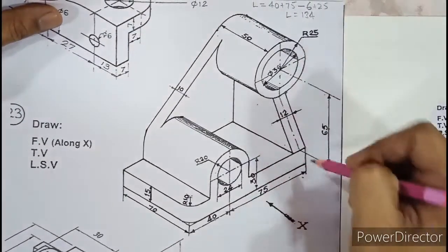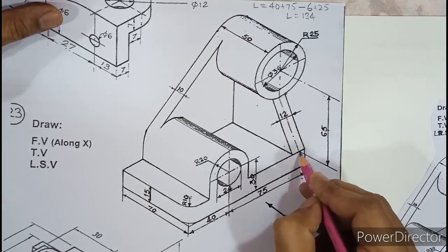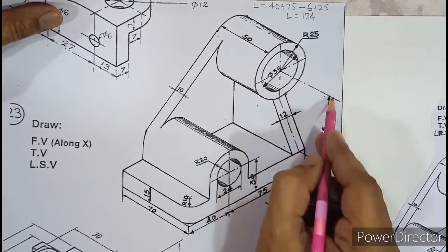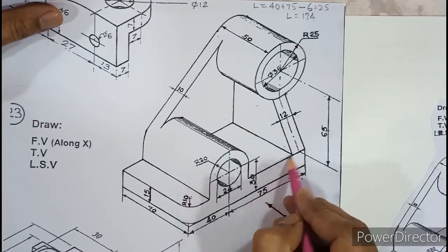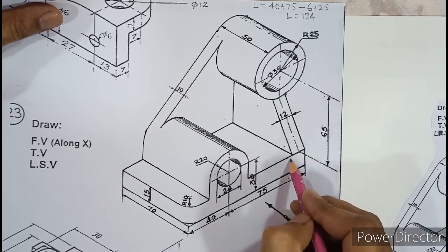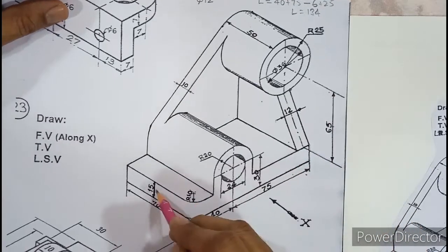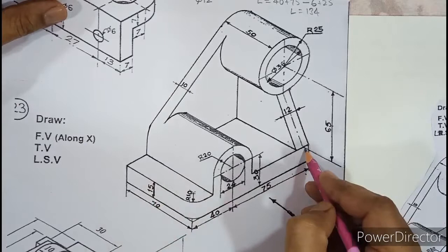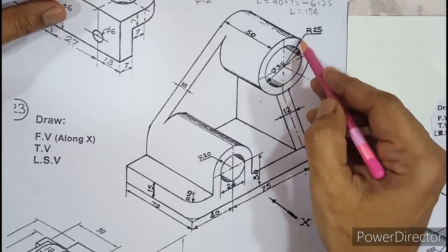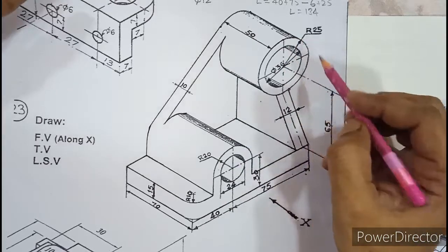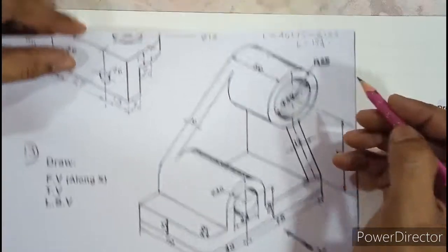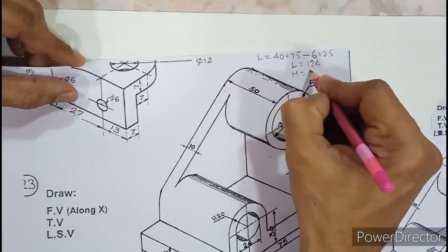Now height of the cylinder. From bottom you need to add the thickness of the plate because 65 mm this height is from the center of the circle till the top of the base plate. This is the base plate. So 65 is till the top. So you have to add 65 and the thickness of this plate, that is given as 15. So 15 plus 65 and radius of this outer circle is how much? 25. So you have to add 15, 65 and 25. So the height what we will be getting is 105.